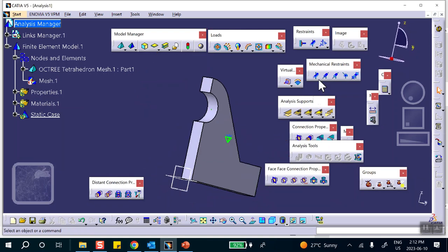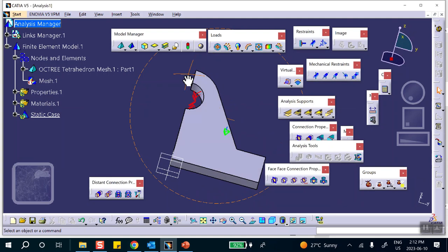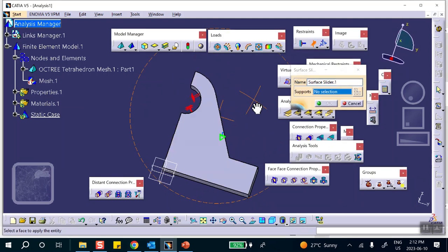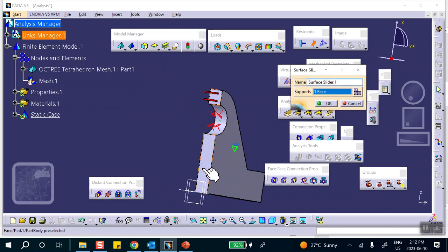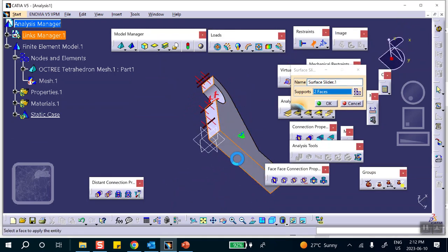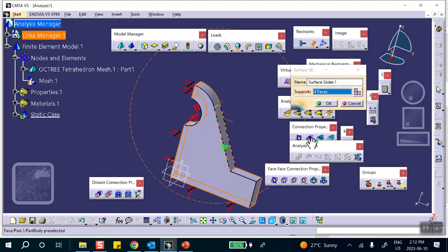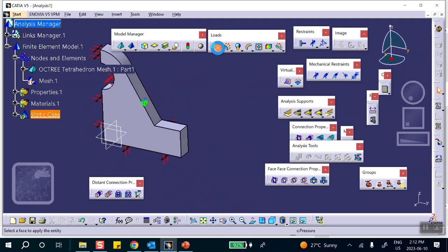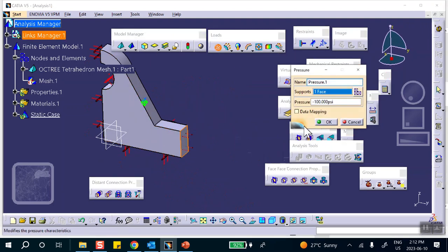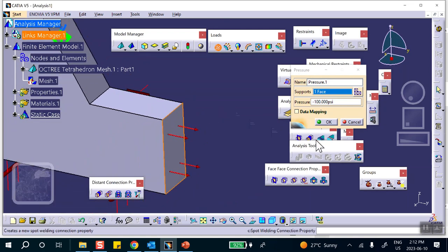All right, so we know that the inside of this is clamped. And we have surface sliders because we have used symmetry to cut this thing many ways. So this side, the bottom side, and the back side, or the entire front side, it really doesn't matter. You say okay, and you are applying a pressure to that face, and the pressure is actually pulling, so that's correct, tensile, and the value is 200 psi.